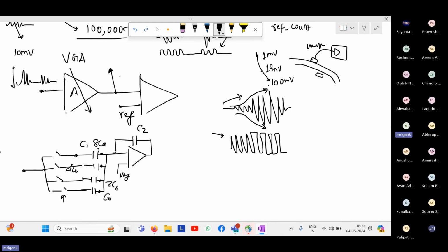And remember, these switches are ultimately TGs, transmission gates. All of you remember the transmission gate? I think in some lectures it has been covered. Ultimately, if you are turning it on, you have to apply VDD here, ground here, and what else do you need? You need something to register the state. So you need a flip flop which you can program, depending upon your tuning option. This is Q and this is D.